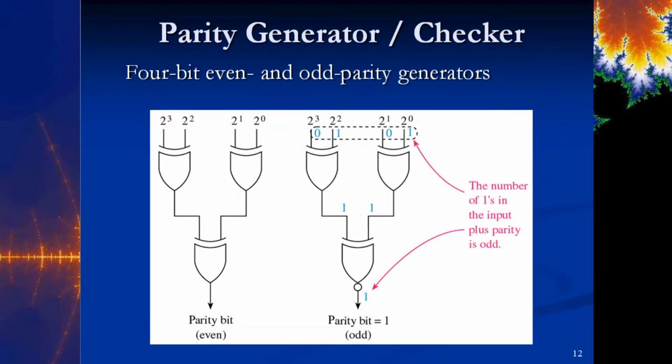So we can set this up with a bunch of different exclusive OR gates. Okay? And so again, if it's an even parity, we exclusive OR all the inputs together, and we have a final gate of an exclusive OR. If it's odd parity, the only difference between exclusive ORing all the inputs together is that the last gate is an exclusive NOR. That's it. There's no other difference between the two parity systems. Okay? And again, this is the parity bit that's going to be generated in this case. All right.